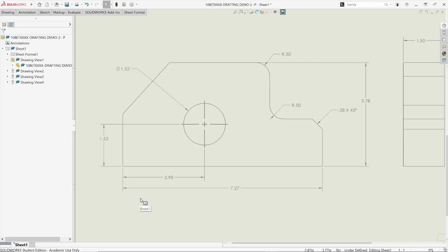One of the most common questions I'm asked is, how do you know which dimensions to create? Well, I get asked this a lot by engineers, new drafters, people that are not experienced with creating drawings. We used to have to think about everything you need to have. So every corner needs a feature dimension to control the size and shape. But nowadays, you don't really even have to think that much because these constraints or dimensions are the same as the constraints in your sketch workbench.